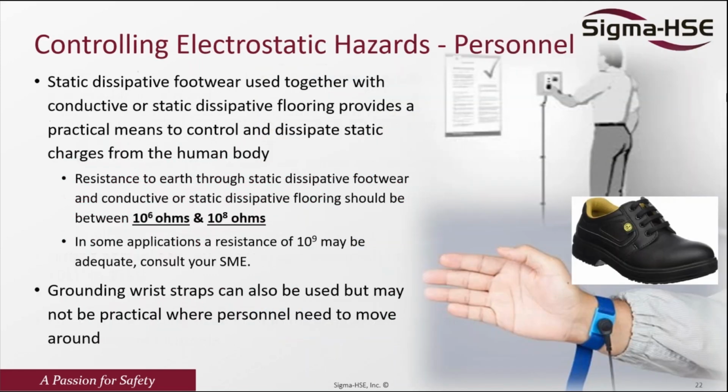So how do we actually ensure that the operators are bonded and grounded? The first one is using footwear. So you can see this one. Normally, most of them have a yellow tag. You can see the picture, the middle picture on the right, and normally it indicates ESD. So anytime you are working in a flammable atmosphere area, we need to ensure that you have static dissipative shoes.